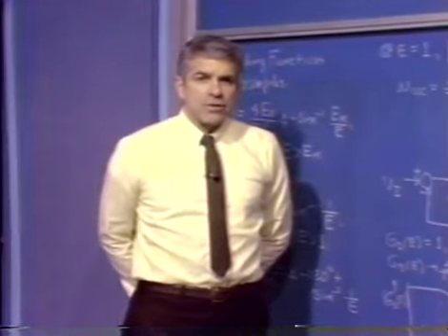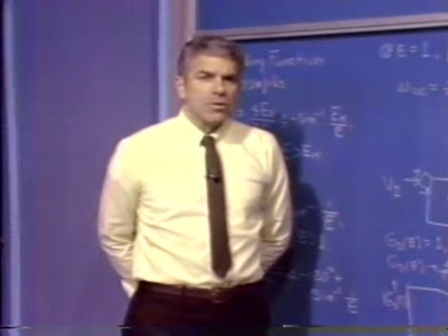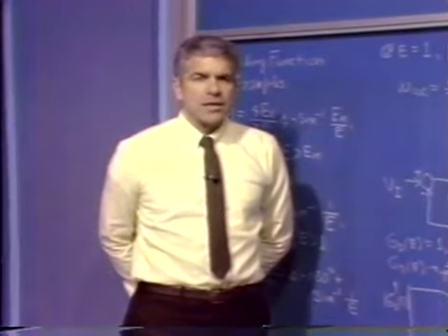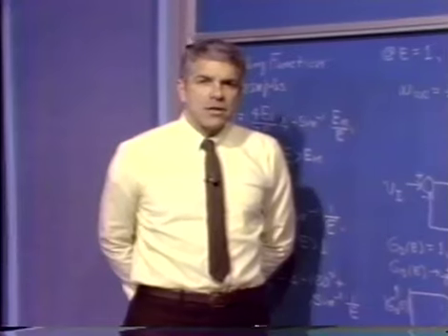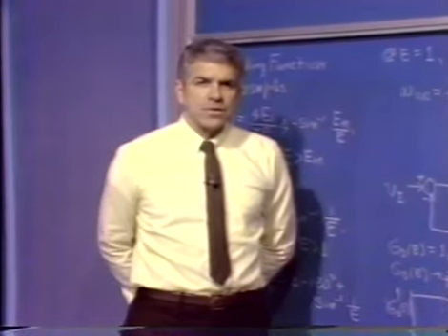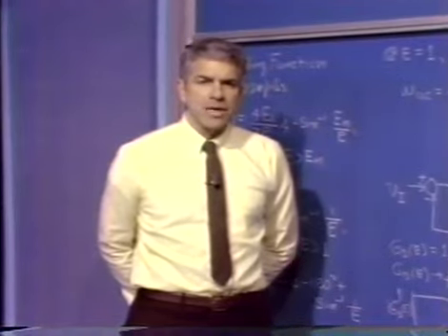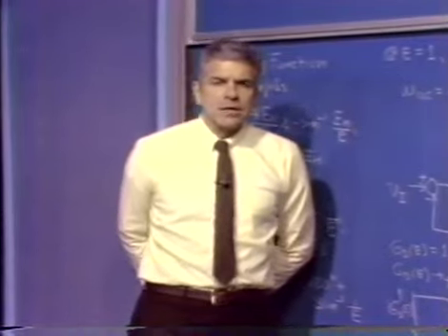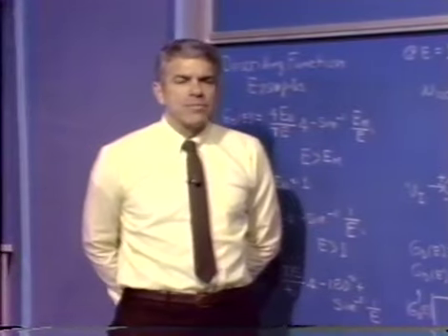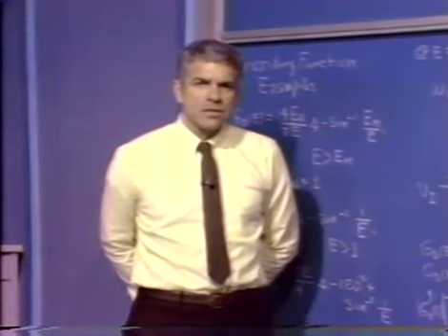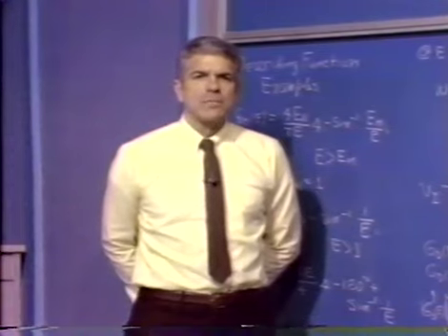We notice that the intersection occurs for a value of E equal to 1. However, that E in that analysis is predicting the value of the fundamental component of the signal. For a triangle wave, the fundamental component is actually about 8/10 of its peak value. So again, depending on how we interpret the magnitude part of the analysis, there's a roughly 20% error.